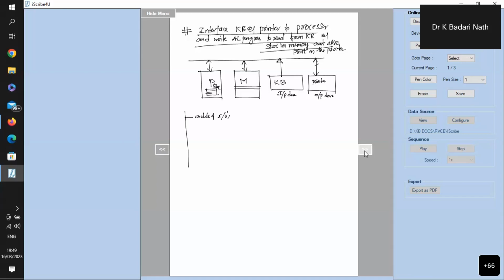So there are two techniques which are popularly provided by most of the processors. One is called IO mapped IO. This is a technique where the addressing of IO devices is taken care of. The other is called memory mapped IO. These are the two popular techniques used by almost all the processors currently available in the market. So Intel processors follow what is called IO mapped IO. That means there are separate instructions called in and out instructions provided to access the input output devices.